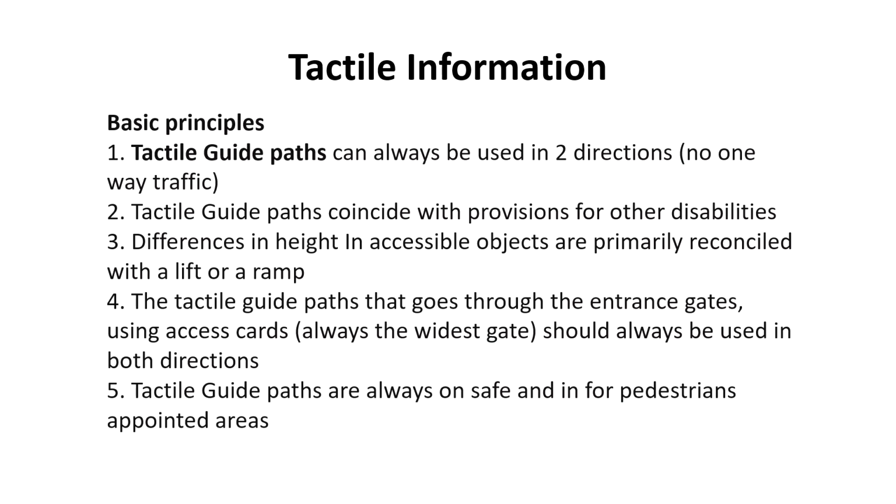The entry gate accessibility: the tactile guide path leading through entrance gates, particularly those operated using cards, should always facilitate movement in both directions, with the widest gate designated for this purpose. Safety and pedestrian zone: the tactile guide paths are consistently located in the safe pedestrian area, prioritizing the well-being and accessibility of the users navigating the environment.